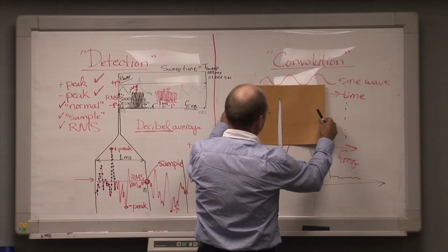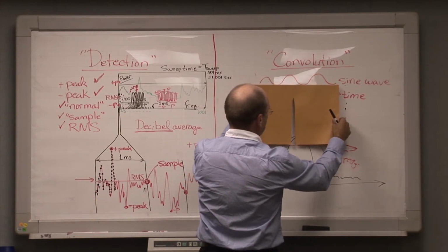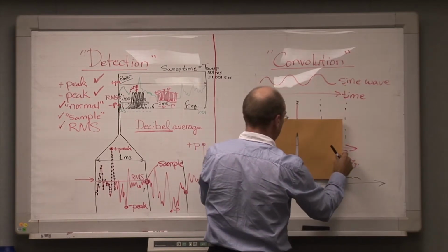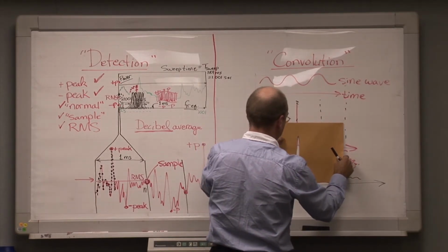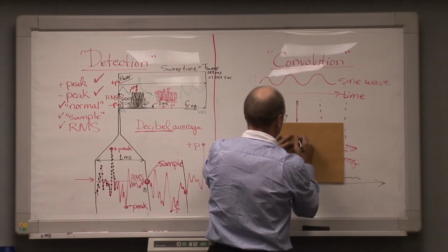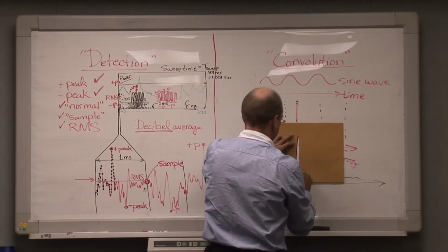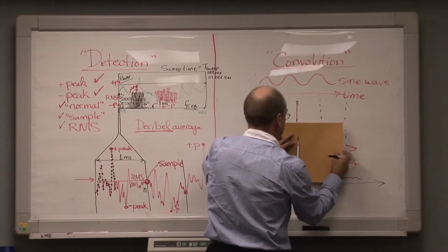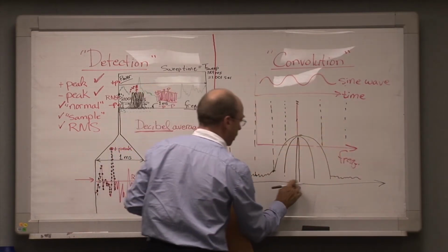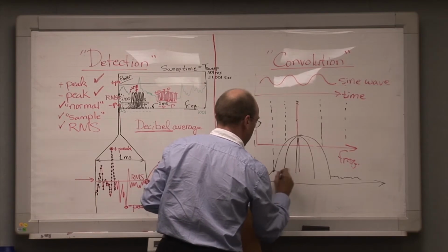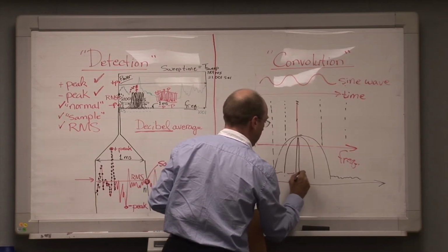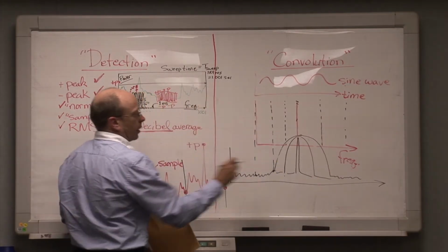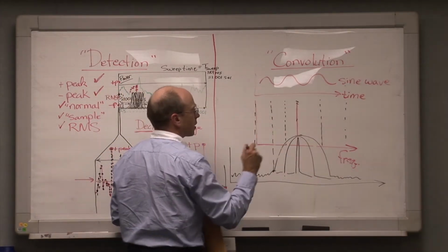Now we come to an even narrower filter, we move it across. It takes longer to move it across, we have to take more steps with it, but we get a little better fidelity picture, like so. And so now with the more narrow filter, the measurement takes longer to run, but we get a better picture of our signal in terms of seeing the width of the signal.